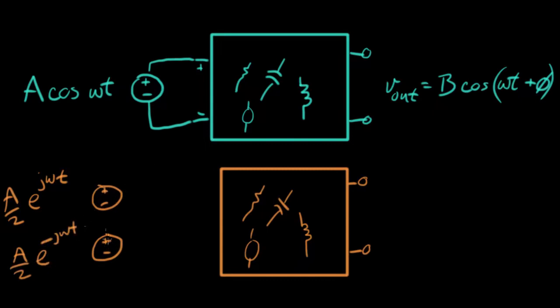That's this waveform. And if I add those together, now remember the equation we just looked at, Euler's formula, says that cosine equals that. The voltage here is exactly the same. And all we've done is describe the same exact cosine waveform as these two imaginary exponentials.